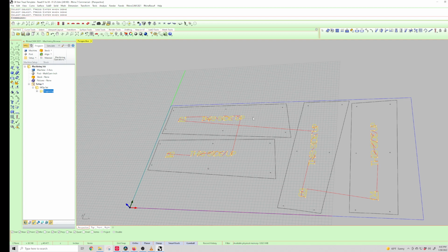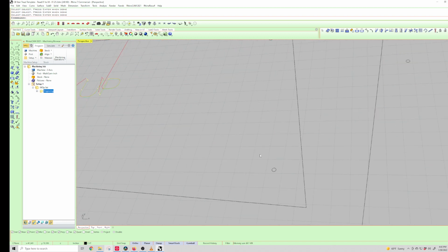We've engraved this lettering here in the top. If we were going to... let's go ahead and do it. I'm going to drill a hole. All of these other holes have just a circle drawn. If this hole was 5/16 and you didn't have a 5/16 end mill, you could go in here with a 1/4 inch and do a profiling pass and have it enter the part like that. In fact, I want to do that so we can show how that would work.